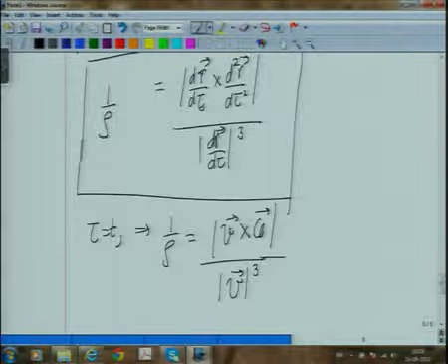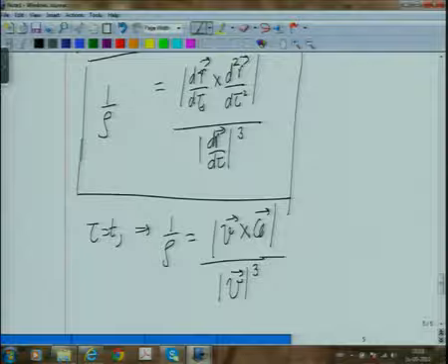There is another thing we have already shown. So these are various ways of finding radius of curvature. If you know the normal component of acceleration and if you know the speed, can you find the radius of curvature? An is equal to v square by rho. So suppose if you know the normal component of acceleration, then you can obviously find the radius of curvature.